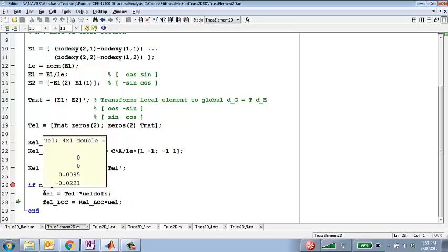And clearly we see that the local displacements in the X prime, Y prime system are 0, 0 at node 1, because of course node 1 doesn't move, and some small number in X prime and some number in Y prime. Okay. Now let me ask you this: what is the change in length of the element if we know that this number is X prime, this number is Y prime? What is the change in length of the element?